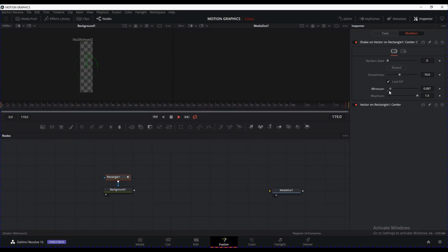So we can just start to push them down. Say we'll bring the maximum down so it doesn't go all the way up there, and then we can also set the minimum. The minimum is up to 0, but you can always change that by putting a negative value. So I'm going to put -2 to just expand it, to bring it back, and now it gives me the ability to bring it back up. So the minimum's there, but just move it until you get a value that doesn't show you the bottom pivot. I just wanted to animate from here to here. So let's bring it down a little bit.